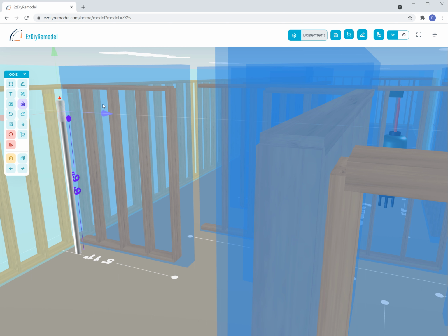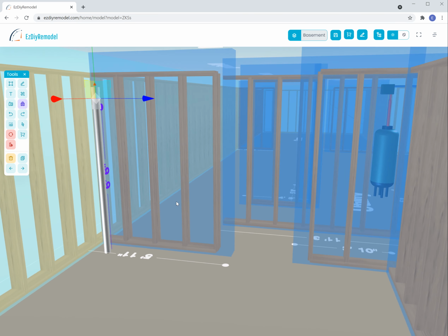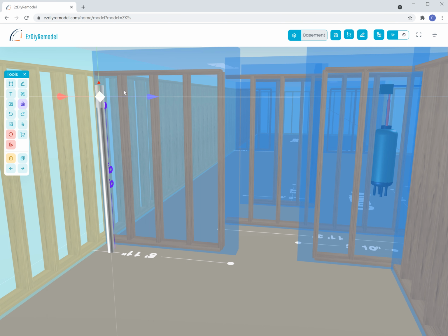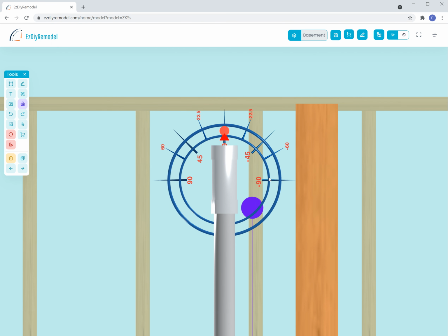Our studs are 7 feet high in the basement, so this top section is 7 feet. So this is gonna go below the joist. So it's 6'6", so I'm gonna be okay turning this way. Because in my case, my main stack goes horizontal and it goes up through a wall. And that's where the toilet will be. So typically this main stack will be exactly where a toilet will be located, maybe 2 toilets. So I'm gonna switch here, change the direction because I wanna go horizontal.